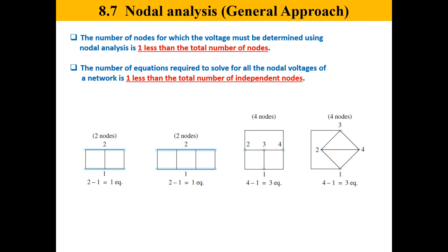The nodal analysis method is another systematic method that can be applied to any circuit to find the voltage of the nodes, and from the voltages, of course, we find currents and powers. The question is, what do we mean by a node? A node, in general, is any point where 2 terminals are connected to each other. So it's an interconnection point where 2 or more elements connect.